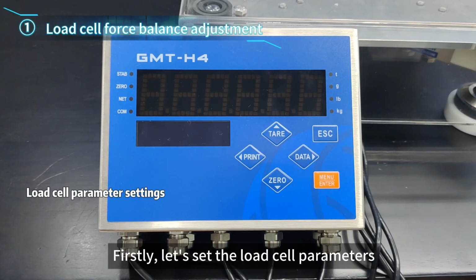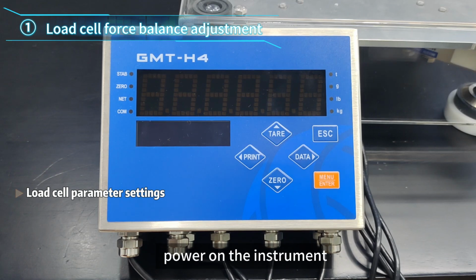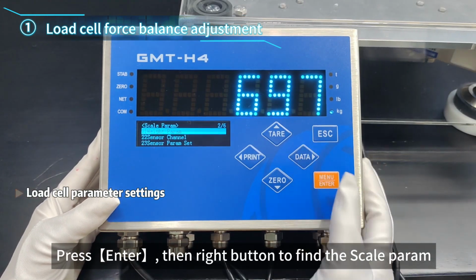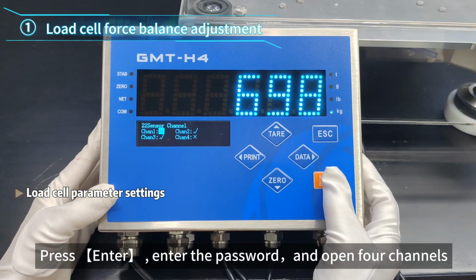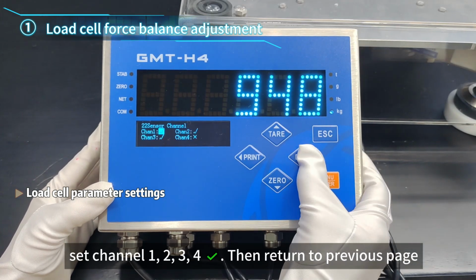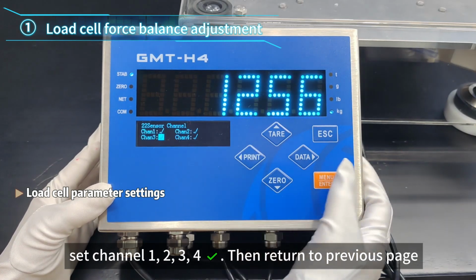Firstly, let's set the load cell parameters. After load cell installation, power on the instrument. Press Enter, then the right button to find the scale parameters. Select the sensor channel, press Enter. Enter the password and open 4 channels. Set channel 1, 2, 3, 4 as a tick. Then return to the previous page.